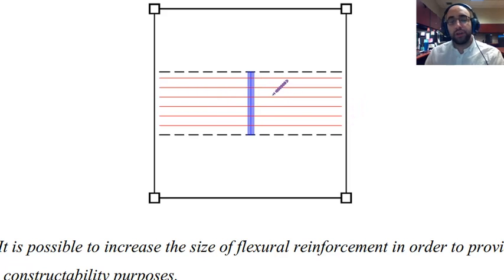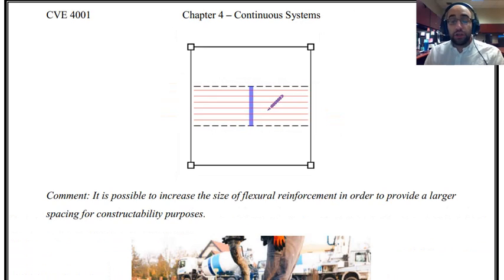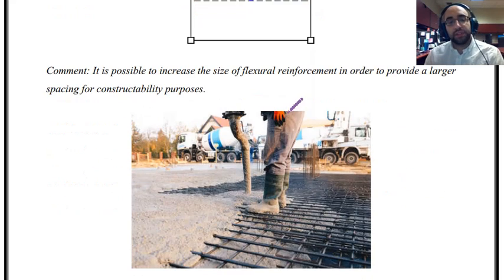and as you can see, these are in the transverse direction. Load is distributed like this. That's why we have the flexural reinforcement in this direction and then the shrinkage reinforcement. As I told you earlier, and as you remember, I said there is a third condition when we are designing the reinforcement, specifically the spacing, and that is whether it is possible to construct it or not.